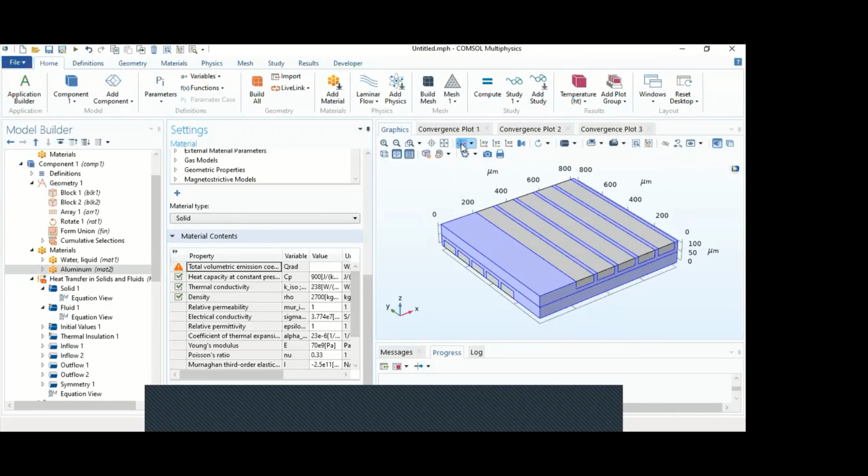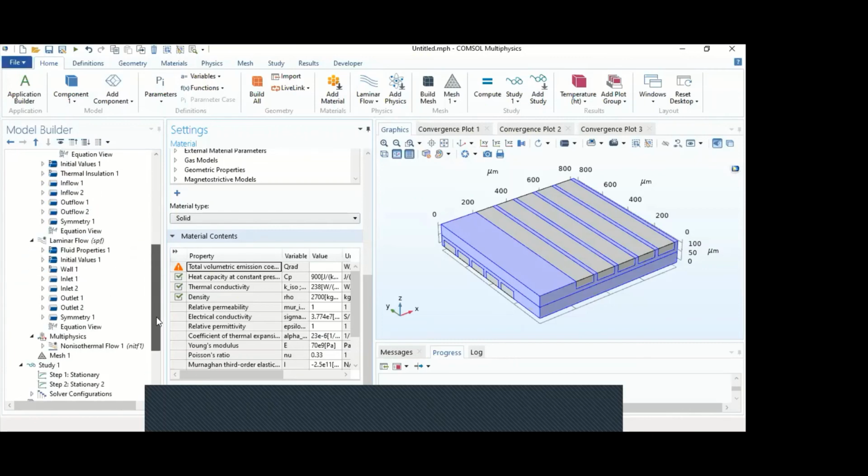If you're using something with frequency domain calculations, there are some equations or some functions that you can use to relate the maximum and minimum mesh element size to the frequency you're calculating at, or the wavelength. And you can find these in some references. It depends upon what actually you're doing.